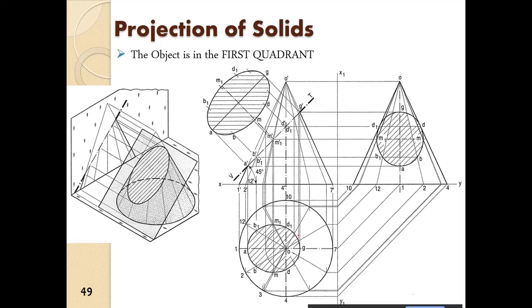Here the diameters are not shown. So we divide: one section here, two section here, three section here, and this is another section. Dividing that, we draw circles, and then we drop the intersection points here. So we get two intersection points, and ultimately we draw the ellipse.